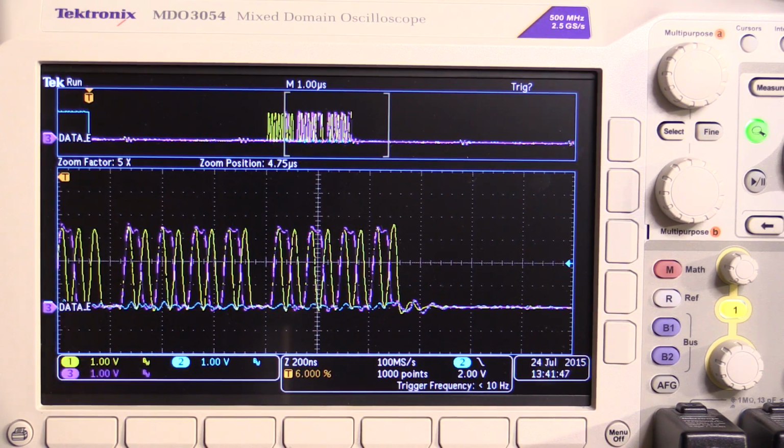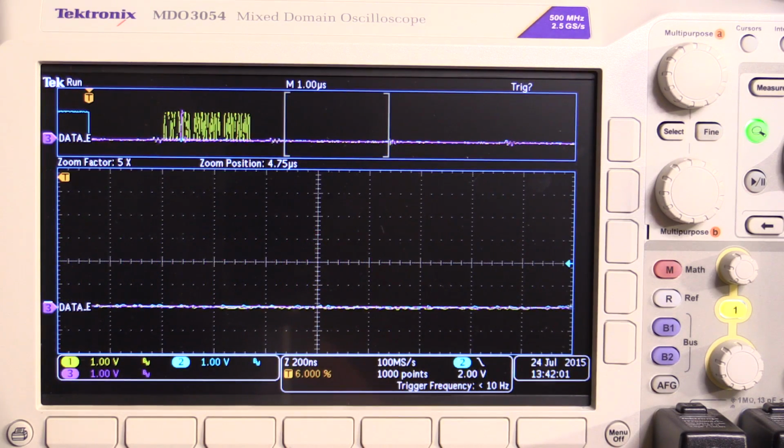If I actually power up my meter, I can tell you, I'm not going to change it from the scope. But if I put in some other values right now, so let's put in 0, and yep, that's still working just fine. It gives me 0 volts. And if I put in 65535, it will give me the 10 volts.